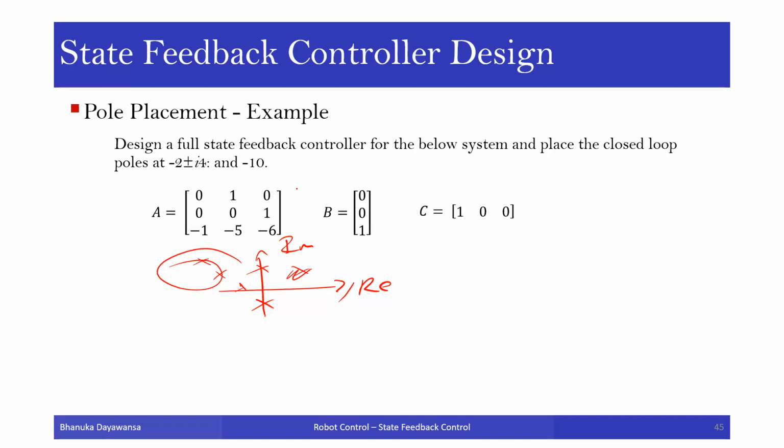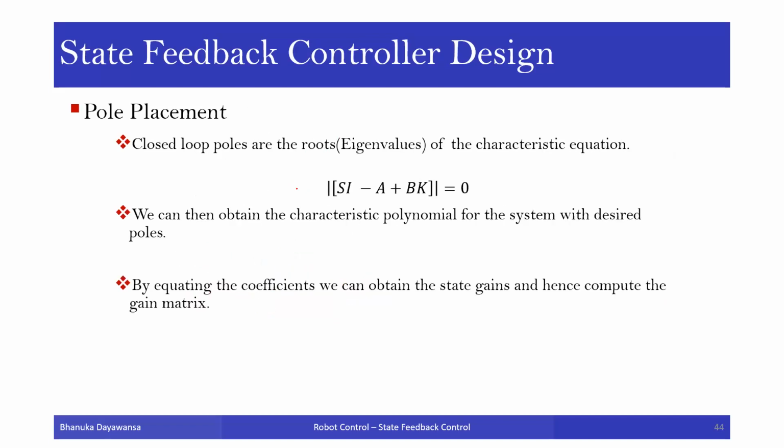In traditional controls, we have a Bode plot or root locus. We find out where the pole placement needs to be done to obtain the system stability, and we place the poles. For a traditional system, you have this characteristic equation, G(s) over 1 plus G(s)H(s), remember? Similarly, the equation for a state feedback controller or any state space model is this, and this is the gain.